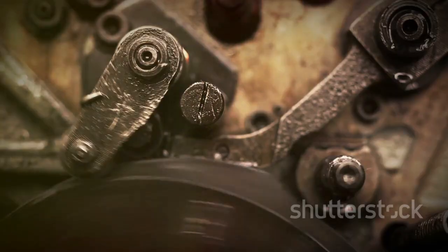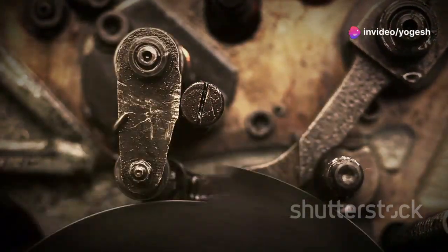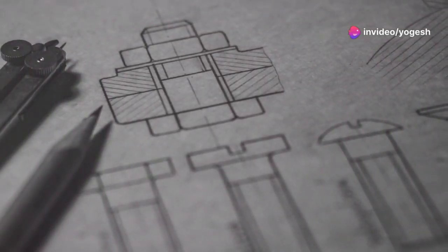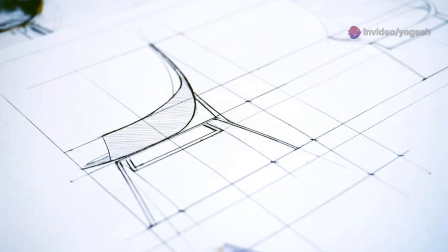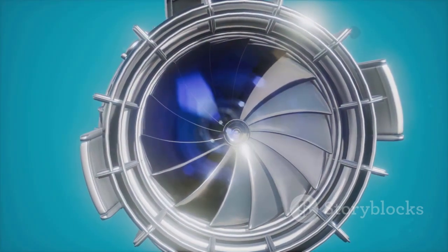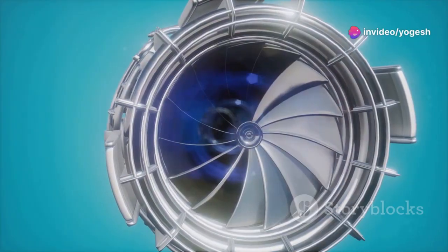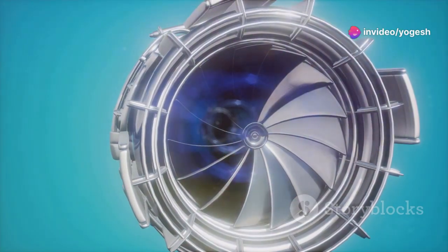This is vital for parts that must fit together perfectly, like dovetail slides in machine tools. Dovetails have angled sides. Only an auxiliary view shows their true profile for precise machining. For complex parts, like turbine blades or heat sink fins, auxiliary views are the only way to show the true shape and dimensions of angled features.